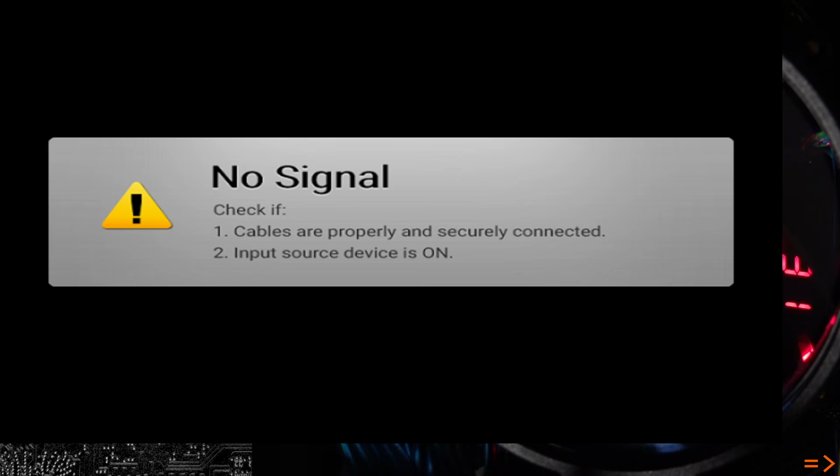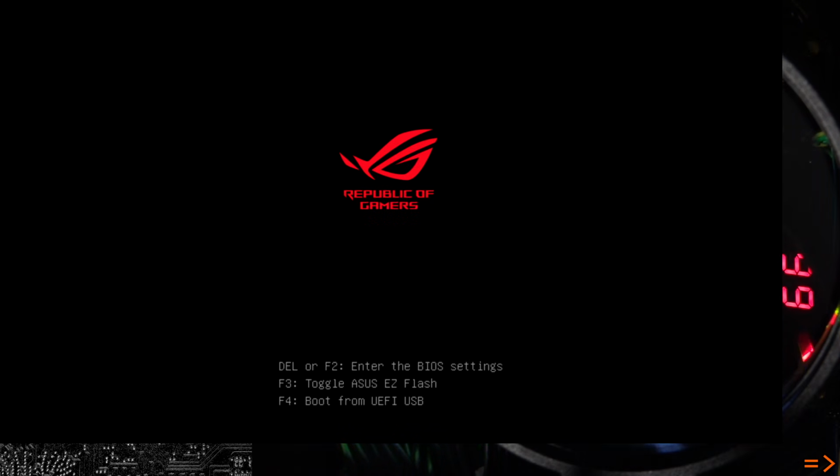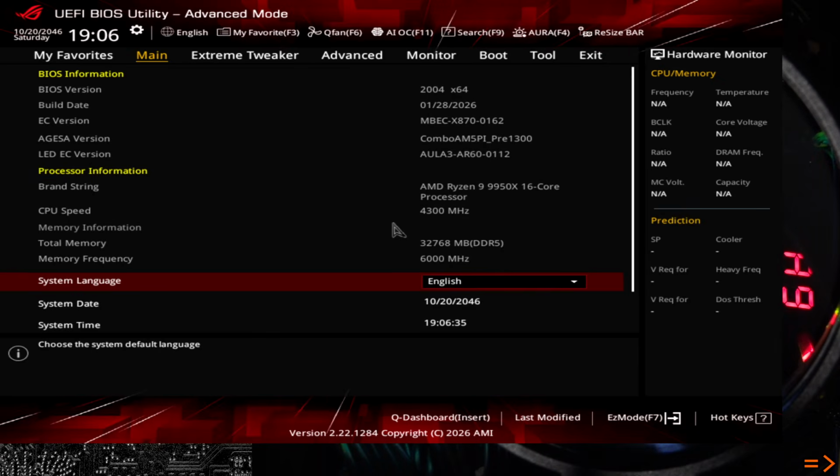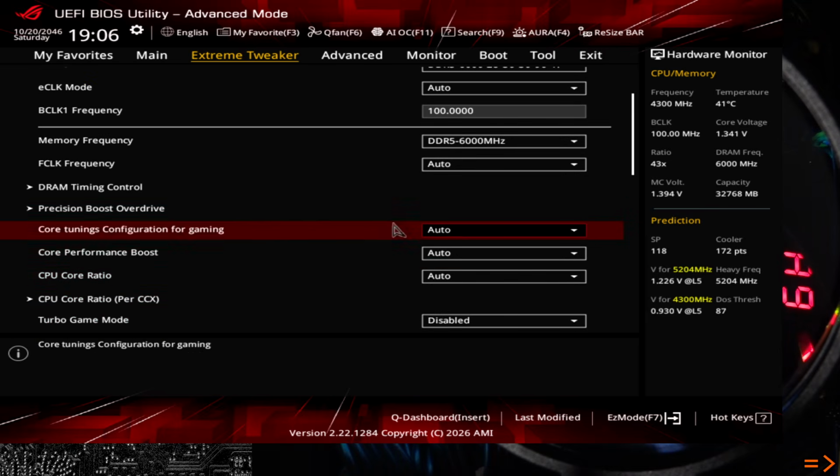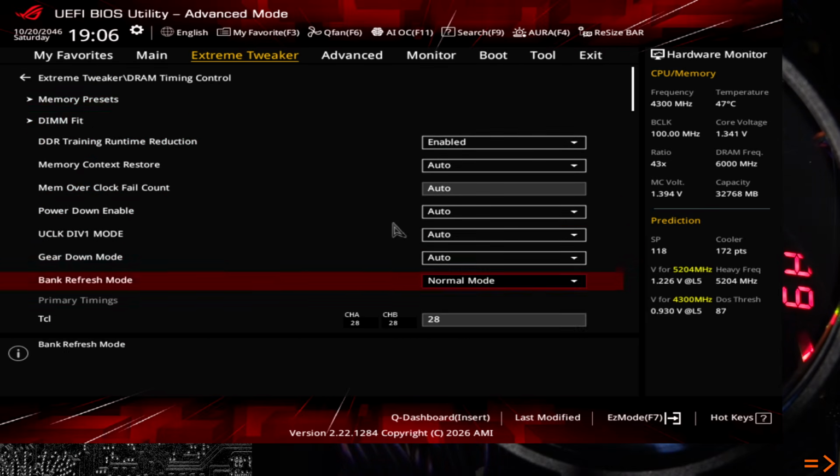So basically, if you have a memory kit on the latest BIOSes, I don't know if there's anywhere in the BIOS that will directly tell you which mode you're in if you don't have the setting available. But basically, if you suddenly have a system where Expo previously worked and it stops working, it's probably because of TRFC2 and TRFC same bank not being set correctly.